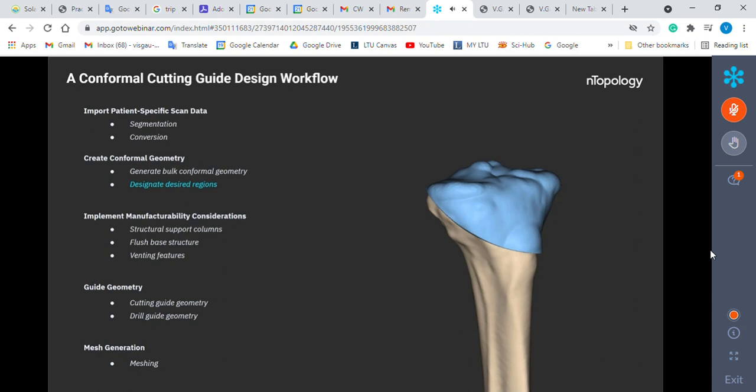Now, while conformal solutions are almost always winning solutions, they don't necessarily accommodate manufacturability right out of the gate. I worked closely with the Carbon team to create some support columns and a base structure that would minimize the amount of sacrificial supports required to print this part. What made this process uniquely easy for us was the ability to effortlessly change design variables such as column height, conical radii, and the base structure parameters. Knowing that the topology software would regenerate geometrically valid results 100% of the time made the iterative process of Carbon completely pain-free as we narrowed in on the most optimal results.